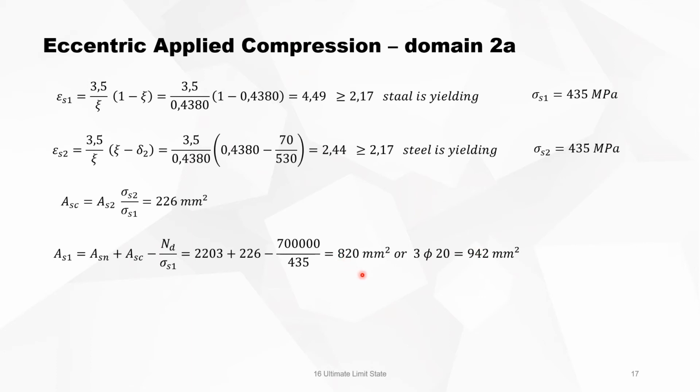you can see we have too much reinforcement. So we can reduce this. We can try 4 diameters 16. It's a little bit short for 4 diameters 16. We can take 2 diameters 25, but that is even more. So we know we have a reserve, but we think 3 diameters 20 is the good one. Maybe we can combine diameters. That would be better.